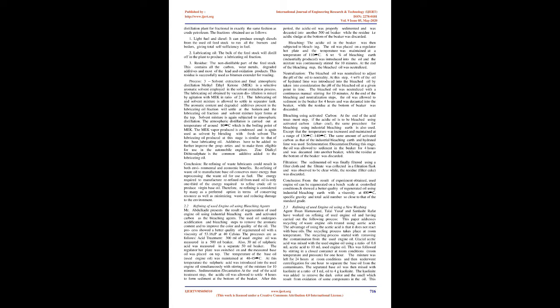Process 2. Vacuum distillation. The vacuum distillation column internals must provide good vapor-liquid contacting while, at the same time, maintaining a very low pressure increase from the top of the column to the bottom. Therefore, the vacuum column uses distillation trays only where withdrawing products from the side of the column, referred to as side draws. Most of the column uses packing material for the vapor-liquid contacting because such packing has a lower pressure drop than distillation trays. This packing material can be either structured sheet metal or randomly dumped packings.